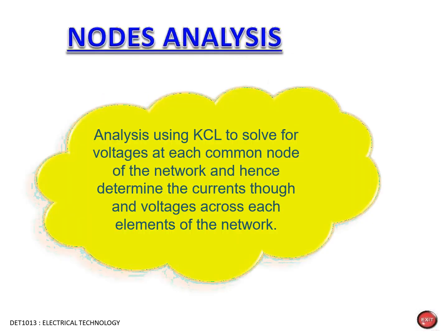Now the next step is nodal analysis. What is nodal analysis and what is the use of it? Analysis using KCL, that is Kirchhoff's current law, helps us to solve for voltages. So Kirchhoff's current law helps us to calculate the voltage at each common node, at each common junction of the network. So in a circuit, when you have to find out the voltage at any point, it can be done using Kirchhoff's current law.